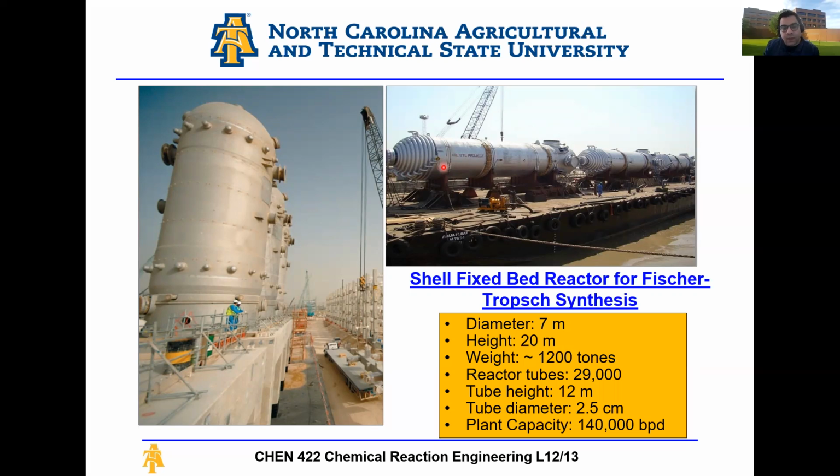Okay, if I compare the performance of this guy to my PFR performance equation, how close will it be? It will not be close, right? You're going to get a lot of differences. And usually your ideal performance equation will give you a much higher performance than what's actually happening in this unit, because your ideal performance equation assumes everything is ideal, everything is nice, happening in your favor.